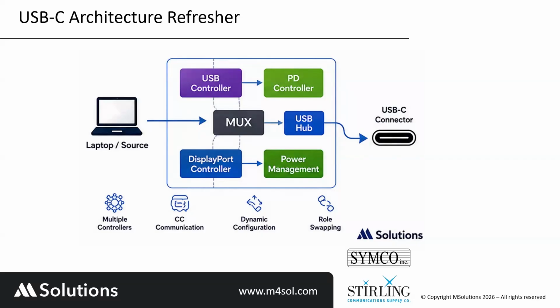We can run from 5 volts in traditional USB to 28 volts in high-power designs. And it can be reversed, meaning what we know today as source and device can be swapped during the negotiation. A laptop can be a device in terms of power, because the controller negotiation can decide that now we're charging the laptop, so the laptop is getting the power rather than providing it.